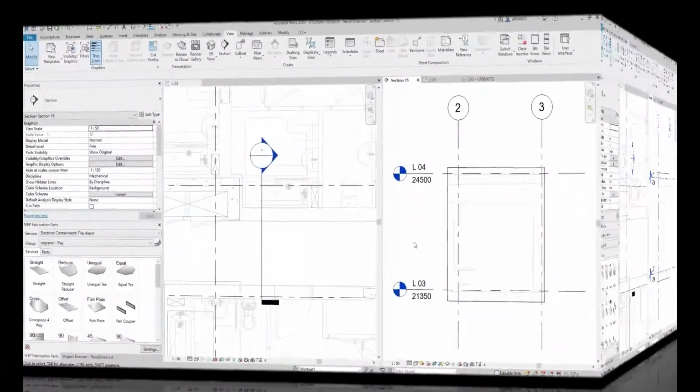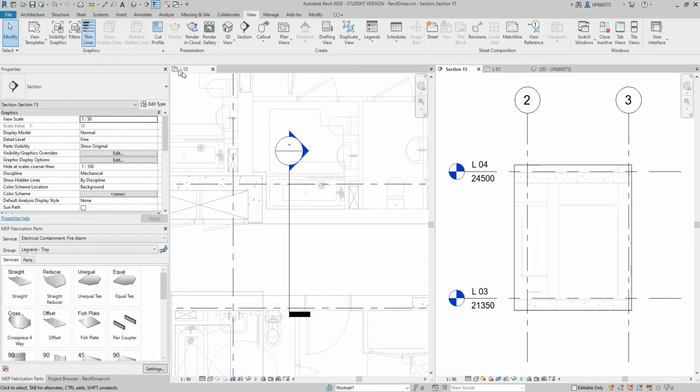Let's say I've been told to work on level 3 and I need to model all the services in the corridors. Straight away I download the drawings the MEP designers prepared for level 3. Normally those are 2D drawings, but sometimes we also get a 3D model, but there are thousands of clashes. Also, I download general arrangement plans, reflected ceiling plans, structural drawings, technical submittals, schedules.